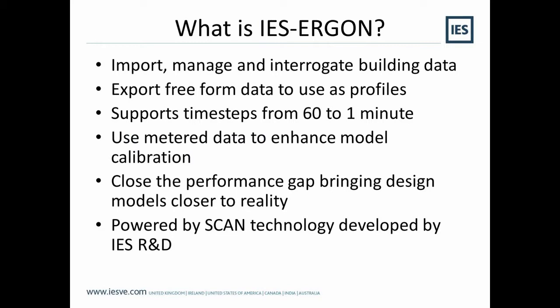Unlike the traditional virtual environment workflow where you're looking at buildings before they're built, the real purpose of ERGON is to deal with buildings which are already built, which are giving you data, maybe from a BMS system, maybe from automatic meter reading technology, smart meters and whatnot. It allows you to collect all that data and bring it back into the virtual environment software, where you can do detailed design using more accurate data.